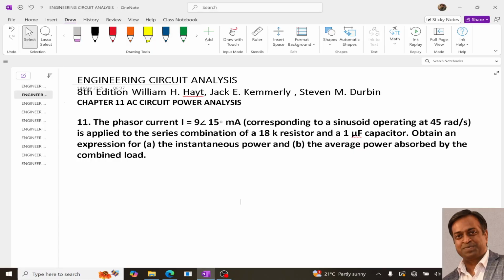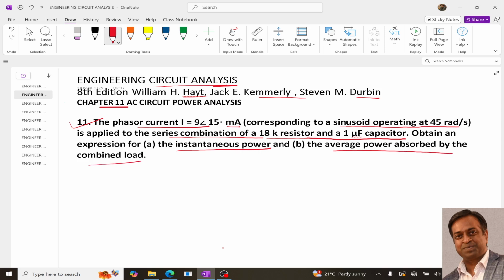Hello guys, in this video I am going to explain the solution of question number 11 from chapter 11 of the book Engineering Circuit Analysis by Hayt, Kemmerly and Durbin. The question says that a phasor current, given in milliamperes, corresponds to a sinusoid operating at 45 radians per second, and it is applied to a series combination of an 18K resistor and a 1 microfarad capacitor. We need to determine the expression for the instantaneous power, and the average power absorbed by the combined load.